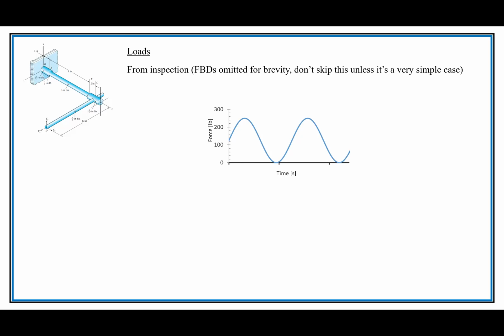The free body diagrams might be necessary, so I think they've been skipped here, but don't usually skip them. It's a simple problem, though, so you could find what the torque is going to be. It's going to be the moment about x, because we have this force y that's coming up, and so it's going to be a maximum of 3,000 inch-pounds.